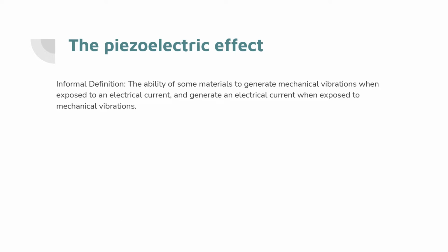Every NDT method is based on certain scientific principles, and ultrasonic testing can be said to be based on the piezoelectric effect. Now, the piezoelectric effect, the informal definition I have for it, is the ability of some materials to generate mechanical vibrations when exposed to an electrical current, and to generate an electrical current when exposed to mechanical vibrations.